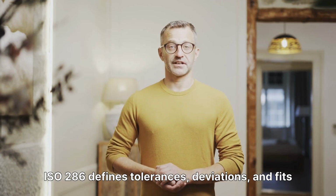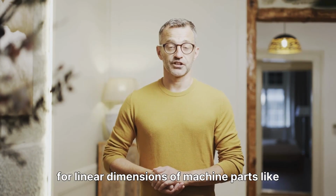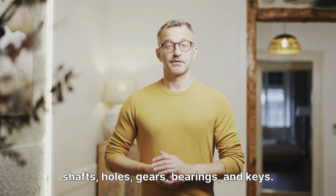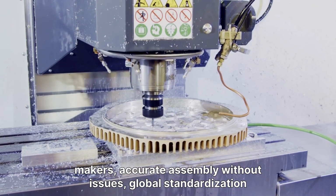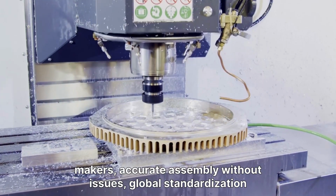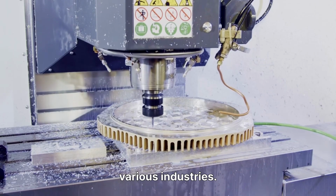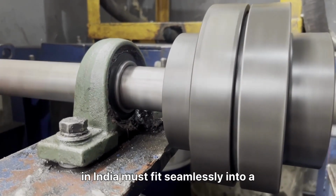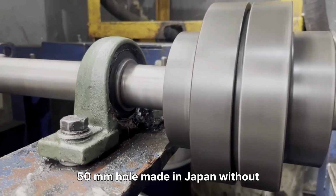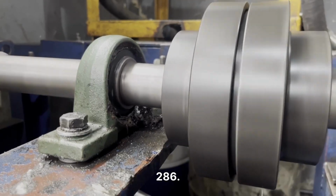ISO 286 defines tolerances, deviations, and fits for linear dimensions of machine parts like shafts, holes, gears, bearings, and keys. It ensures interchangeability between parts from different makers, accurate assembly without issues, global standardization across borders, and reduced manufacturing errors in various industries. For example, a 50 mm shaft made in India must fit seamlessly into a 50 mm hole made in Japan without any separate tolerance discussions, thanks to ISO 286.